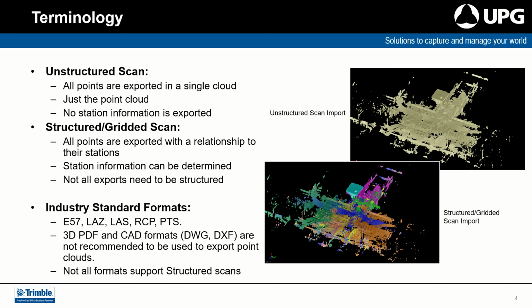When exporting data, it should be a strong consideration to note whether the export needs to be structured or gridded, in which case only particular formats out of Trimble Business Center and RealWorks will support that, and that needs to be selected as an option when exporting.